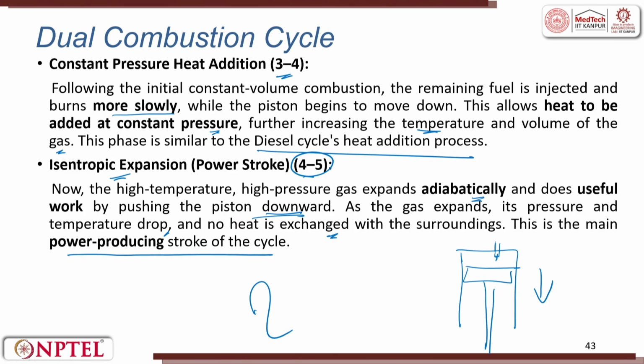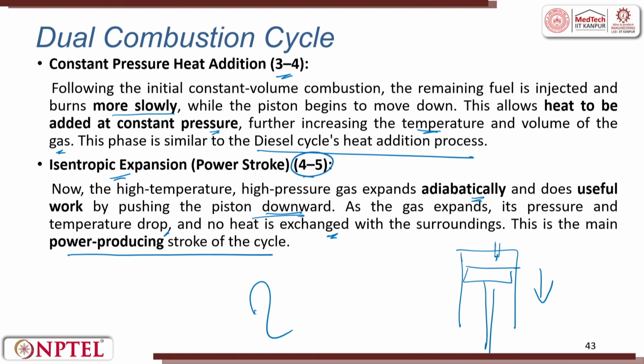For this theoretical efficiency, there will be almost a drop of 50% to the actual efficiency. So if you see the diesel cycle and Otto cycle that we study here, you will try to get efficiency of 40%, 50%. In some cases, academically or theoretically, you can get even 70%. In reality, it will be close to 25%.